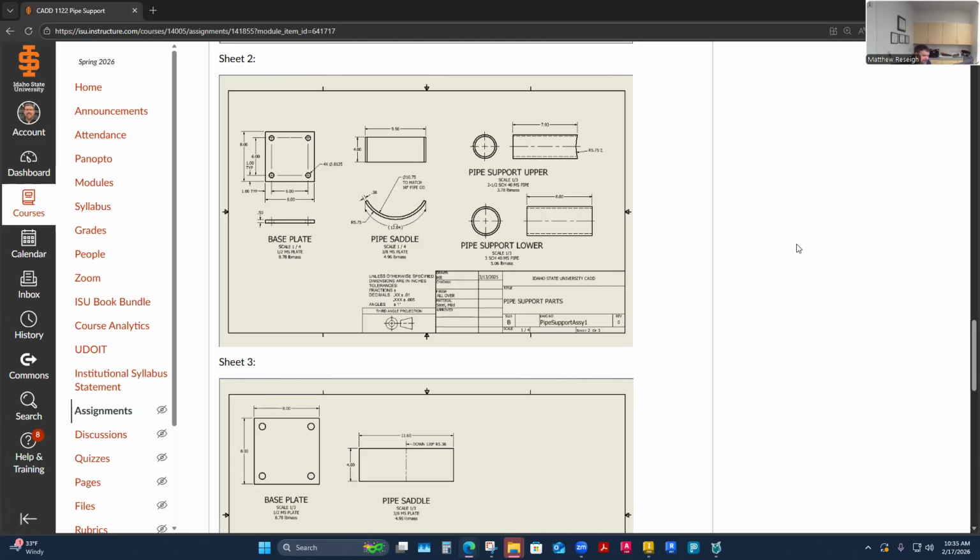It's like a big drill bit with teeth on the outside, a more aggressive looking bit made to side cut, and they can run that into the end. They make specific machines for coping, and a lot of companies do this, especially handrail shops. Handrail shops probably have the best coping machines because handrail involves a lot of coping on different materials. But yeah, super cool.